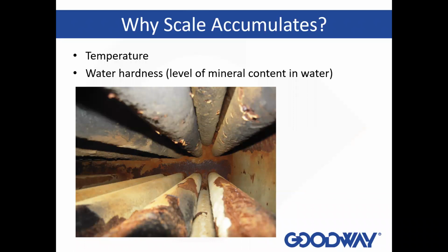Also, a big problem that we've seen is that it's kind of out of sight, out of mind. A lot of times the manhole covers are not really opened, or a glance may happen and they say, okay, it looks all right, and the manhole cover is put back on until an inspector gets there, looks at it, and says the boiler is unacceptable. We can't basically check off on this boiler for its operation until it's cleaned on the water side.